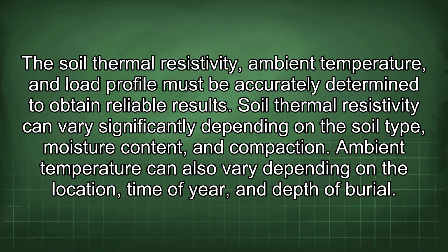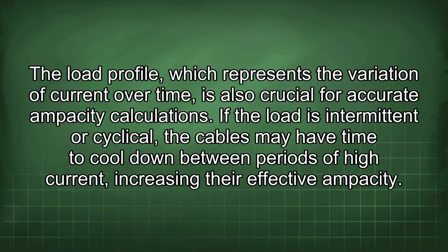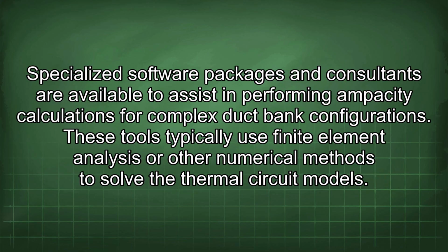Soil thermal resistivity can vary significantly depending on the soil type, moisture content, and compaction. Ambient temperature can also vary depending on the location, time of year, and depth of burial. The load profile, which represents the variation of current over time, is also crucial for accurate ampacity calculations. If the load is intermittent or cyclical, the cables may have time to cool down between periods of high current, increasing their effective ampacity.